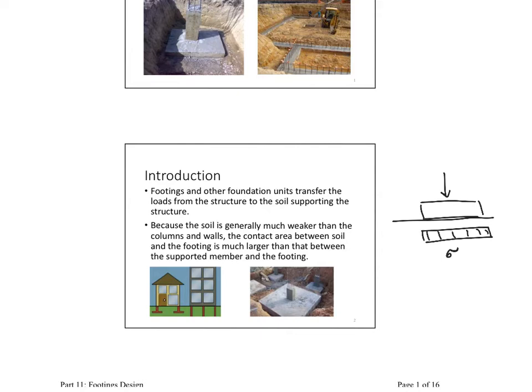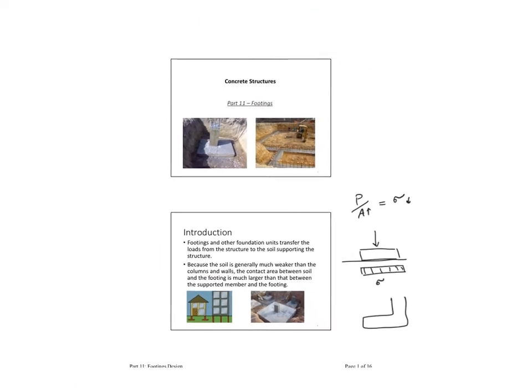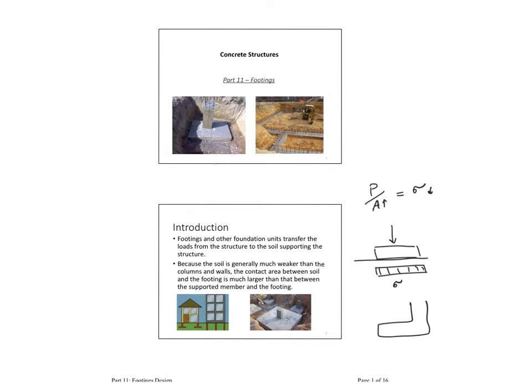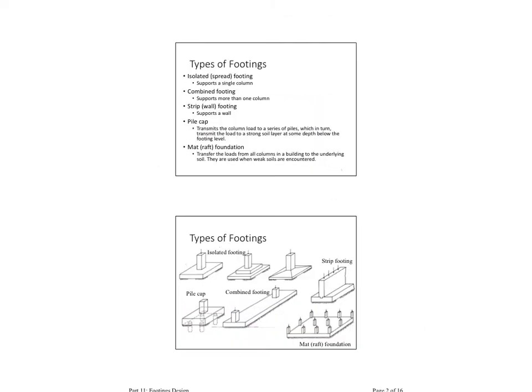And so what this does is actually exactly as your foot. You know, what your foot is doing is it distributes the load that comes on your leg from your body down to a bigger area. And as we know, P over the area gives the stress. So the bigger the area, the smaller the stress will be, right? And if you have a smaller stress, you will safely take that load of the building down to the soil and to the ground. So that's exactly the purpose of the footing.